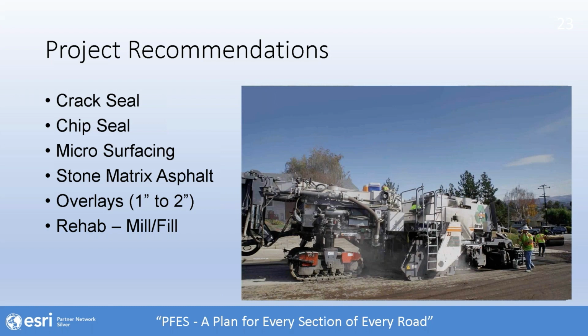But obviously, this is the most expensive treatment. But the interesting thing, working with the clients, they don't have infinite budgets. Most clients will restrict this kind of operation just to high volume roads. So the model will not allow this kind of treatment, even if the road is in severe condition on a low volume road, recognizing that there are only limited budgets to maintain your pavement.